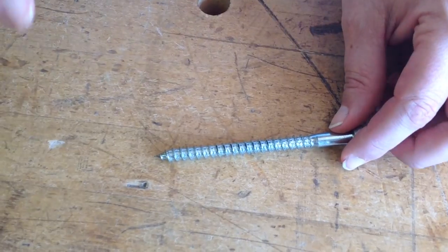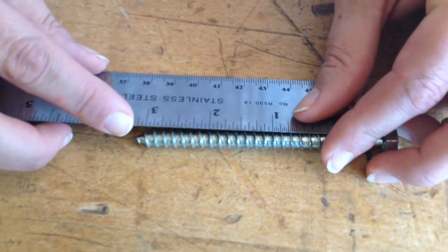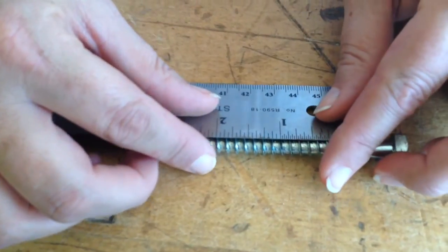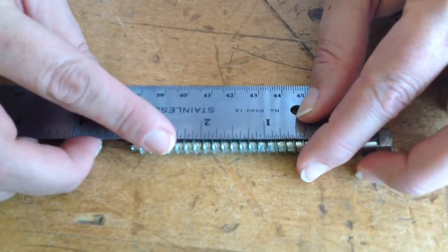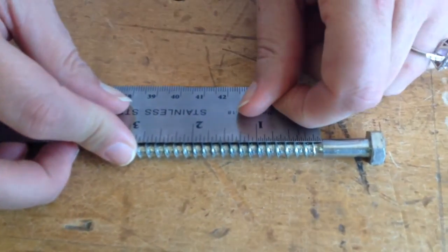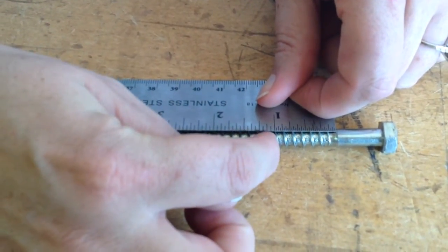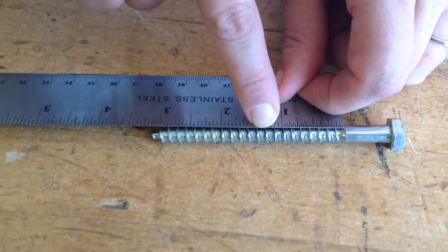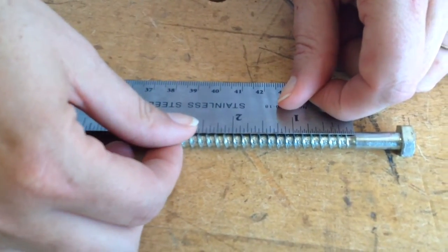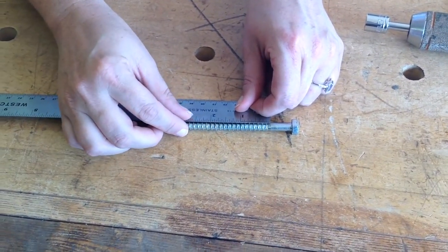So let's go ahead and measure that. Sometimes it's easier to go from just 1 inch in the middle of your ruler because sometimes you lose some at the end. So looking here, you can tell that it's 1/8 of an inch between the two. Or if you're given a full inch, how many is that? We're going to count. 1, 2, 3, 4, 5, 6, 7, 8. So you can tell that there are 8 threads in an inch. And just by looking at it too, we could tell that it was 1/8 of an inch distance that it's going to go down.